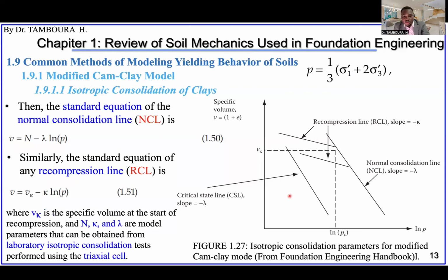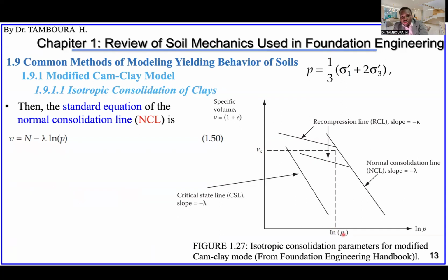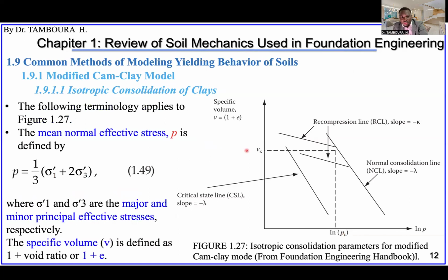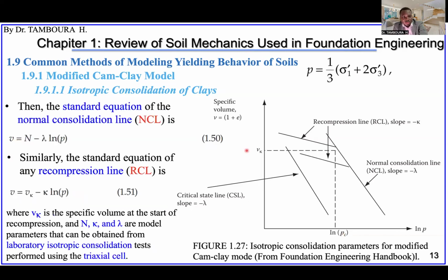Okay, so this VK here, corresponding to this PC. Let me go back a little bit to show you. It is like here, this P, the maximum load that the soil has already experienced, and the corresponding void ratio. Okay, so let's go back. VK here is the specific volume at the start of the recompression here.